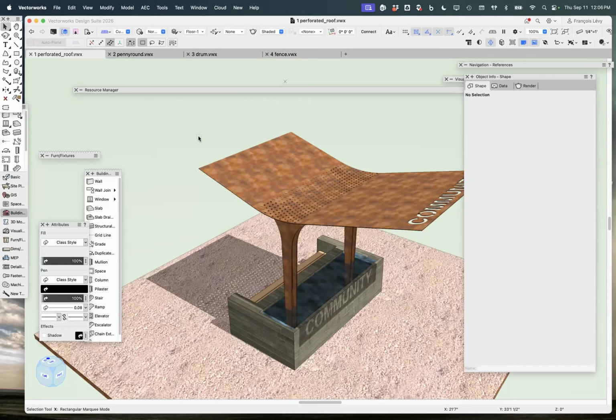Just to back up, I'm going to take a little detour and show you how I made this NURBS surface, because it's really pretty easy. Let's back up a few steps here. Okay, group that. There we go. So here's the geometry that we started with. In this case, what I did is I just started with an extrude along path to make this shape.